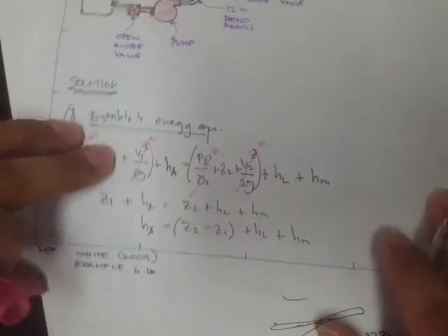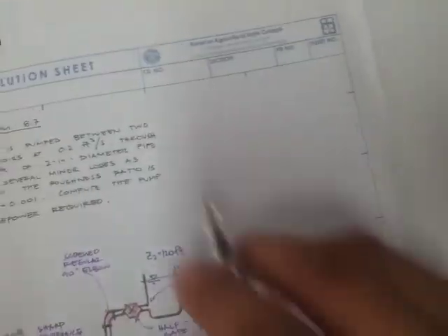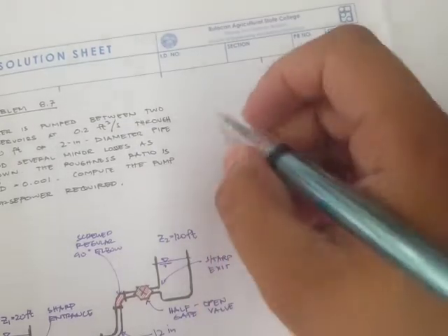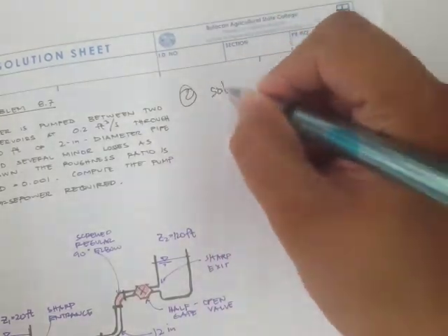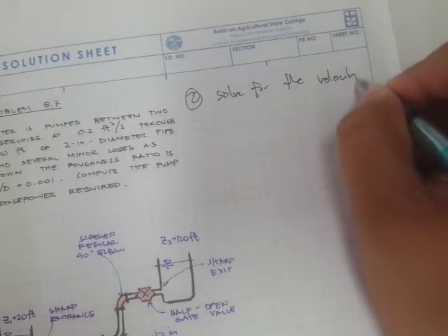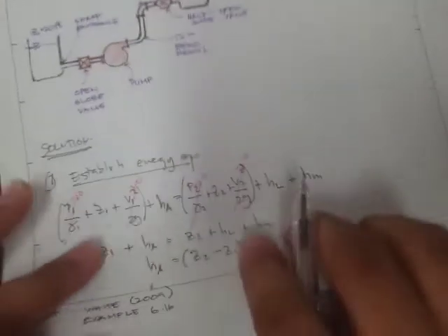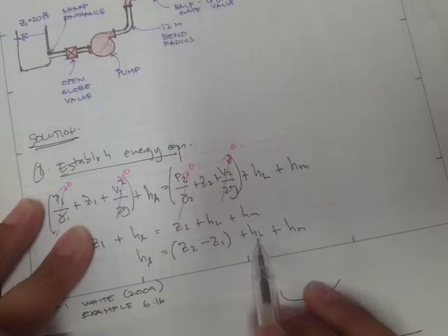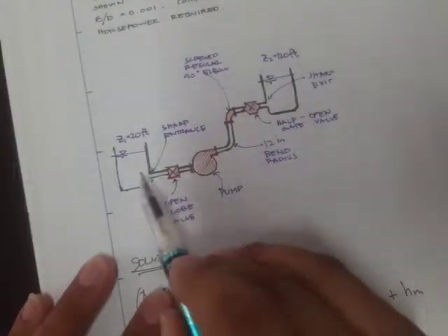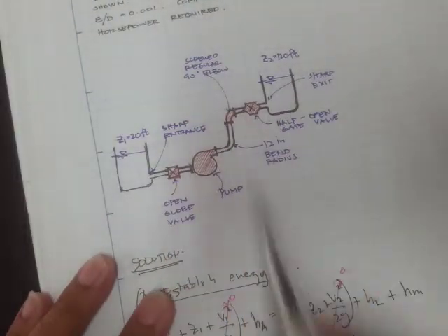Okay, so right, the next step now is to solve for the velocity. We need velocity simply because in this head loss equation we need the v squared over 2g. Also right here we need the v squared all over 2g. So that's the velocity along this pipeline.